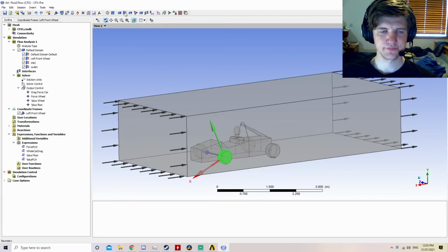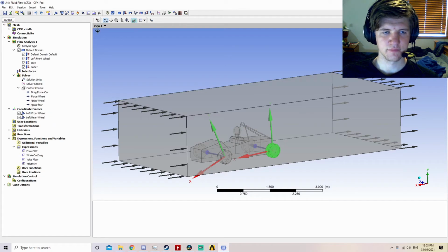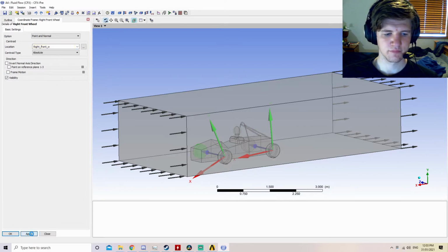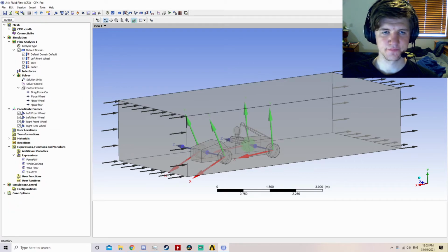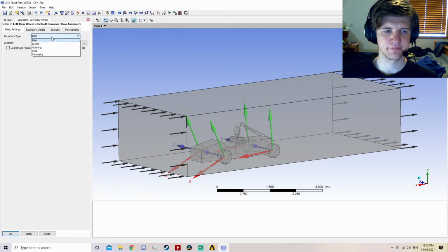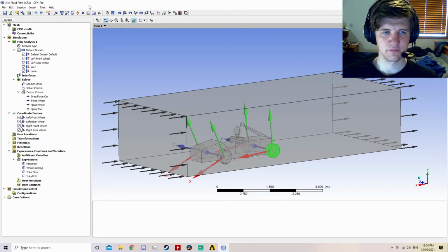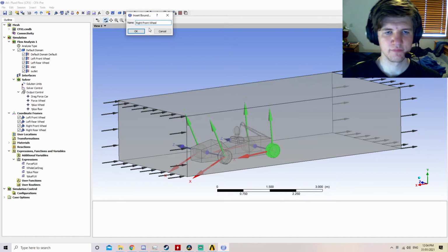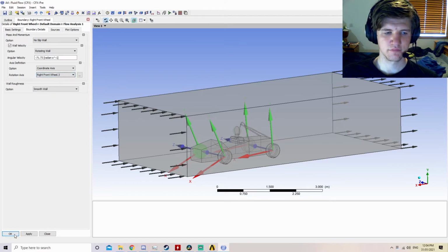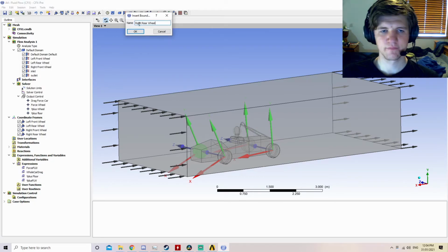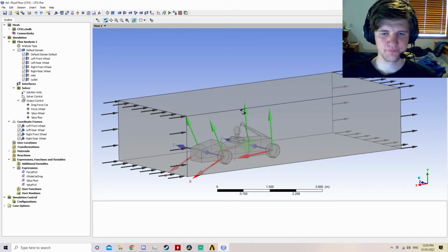Now it's time to let the simulation run to reach a solution. While that happens, I'm here to talk to you about why that's necessary in a whole car package simulation. Although not present on this car, wings will be present on future simulations done in ANSYS. These wings are very sensitive to changes in the air around them, and stationary and rotating wheels give different wake paths and take-up paths of air as they pass through it. Given the team's current desire to improve simulations of the overall package, it is critical that rotating wheels are added into this new simulation style.